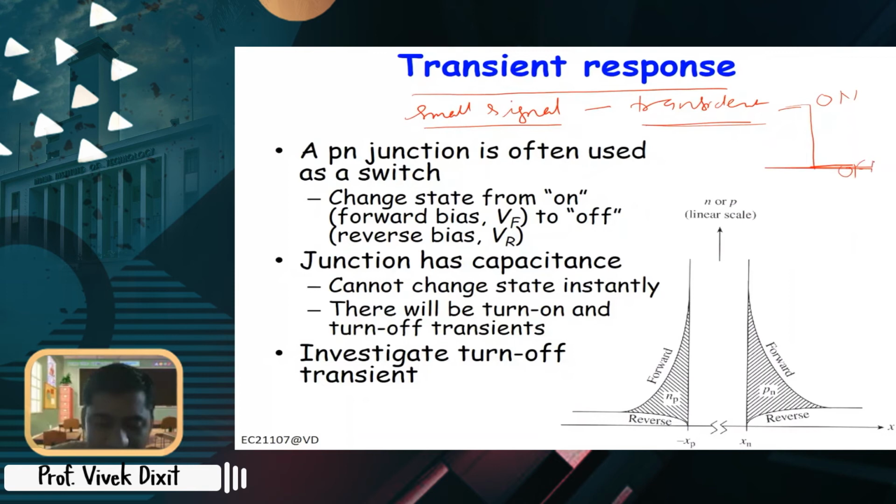It's like a logic function basically, so the voltage range can be larger. If you think of the PN junction as a switch, then it is on around V_BI, or sometimes written as V gamma, the turn-on voltage, and off at a negative voltage. It may not be very large, but a decent negative voltage.